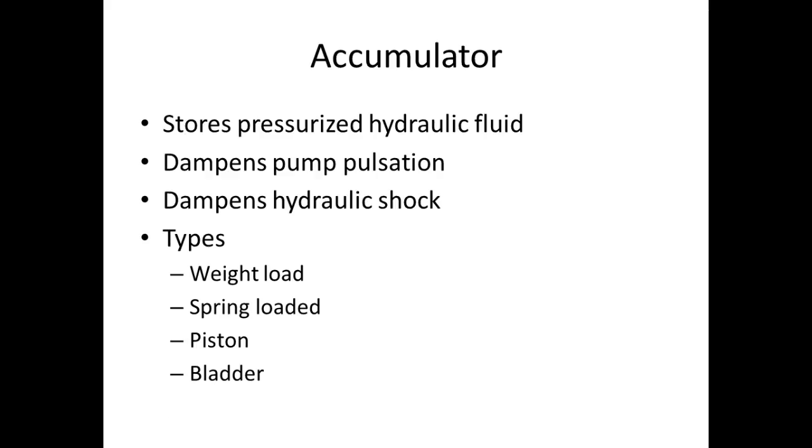Now, one feature that we get from a pneumatic system that has a receiver is that if power fails, we've got that big tank out there charged up, so we're going to maintain pressure, right? This is extremely important for things that are moving things around using fluid power. Because when power fails, if you lose that pressure source, you've already lost the electricity, right? If you lose that other pressure source, then things are going to fall, things are going to drop.